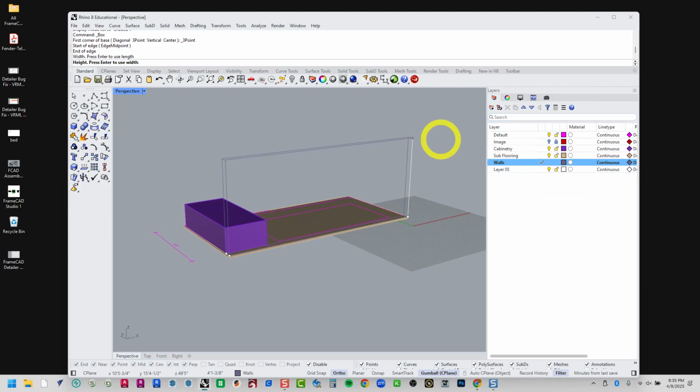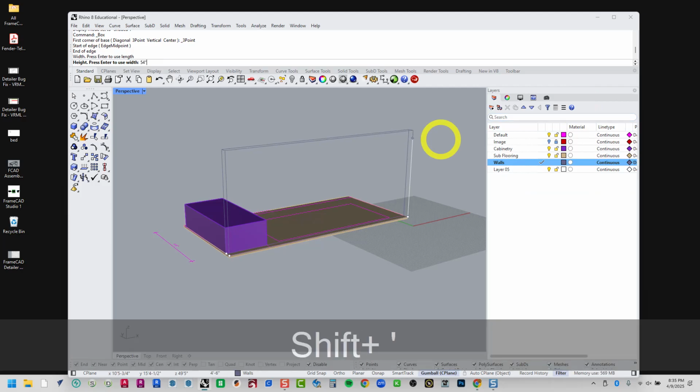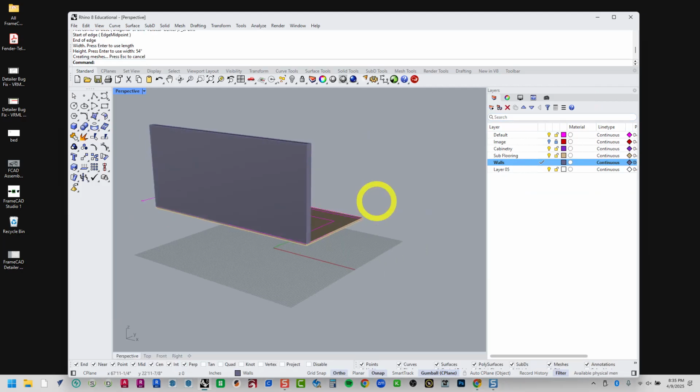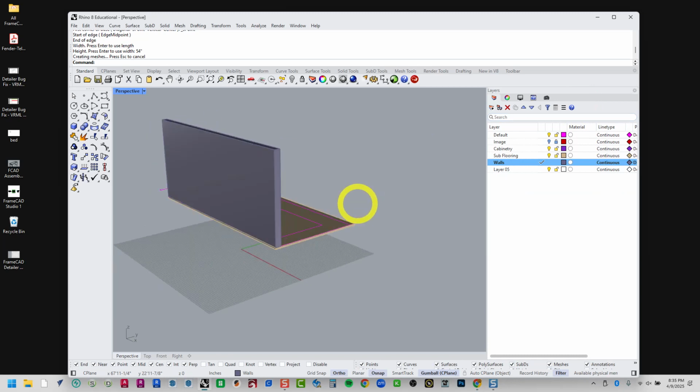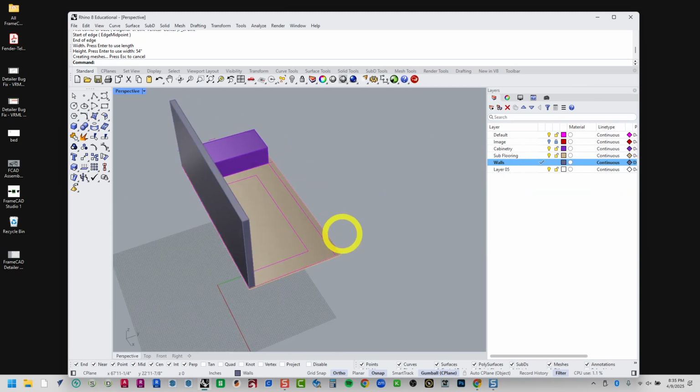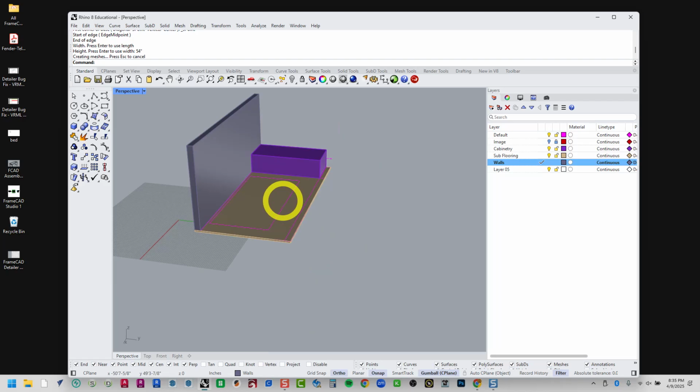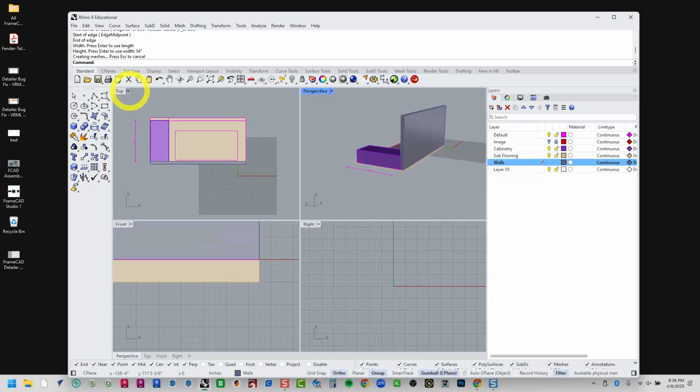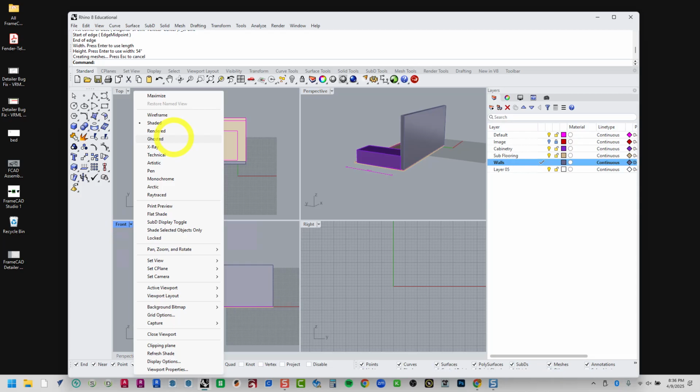So if I draw a polyline and just kind of use this box that I've drawn to sort of sketch some ideas of, you know, where this thing could taper. Maybe I just draw a 45-degree line right there, or turn off ortho and do something a little bit more drastic, maybe a little more Cybertruck looking. Let's put it somewhere about there.